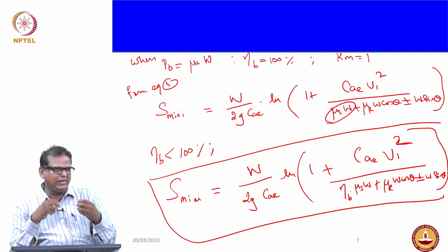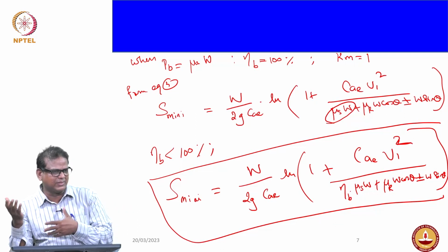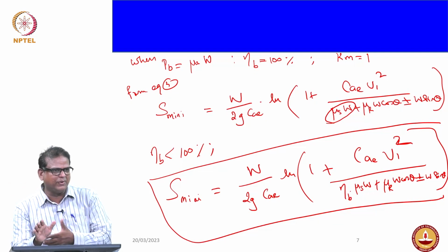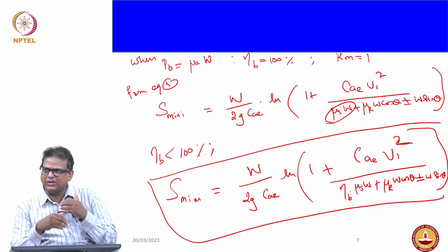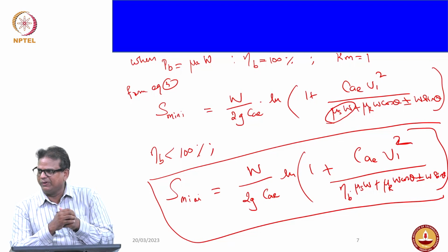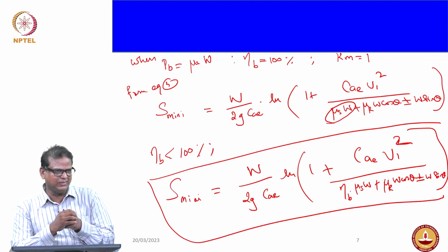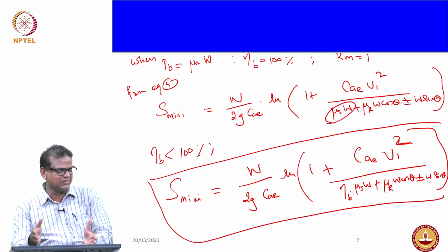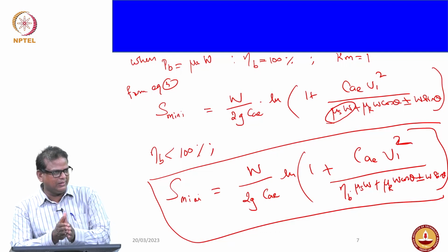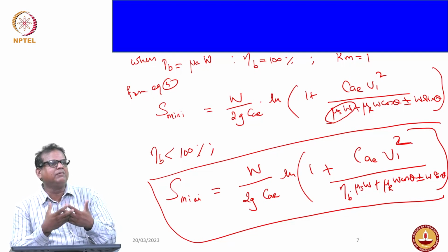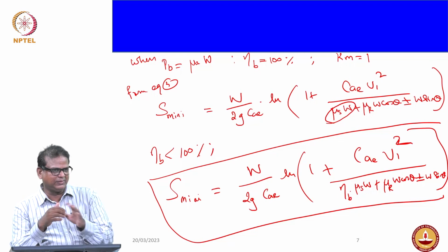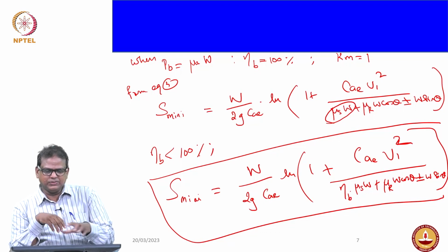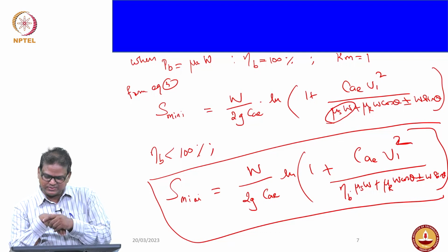Normally the reaction time varies from 0.5 seconds to 2 seconds maximum. Then you apply the brake suddenly, so by that time you would have crossed a certain distance also. You have to consider that when calculating the stopping distance. The braking distance we find now, the minimum distance, is absolute, but in reality we have to include the driver reaction and the consequent distance crossed during that time. So this is for your braking distance aspect.